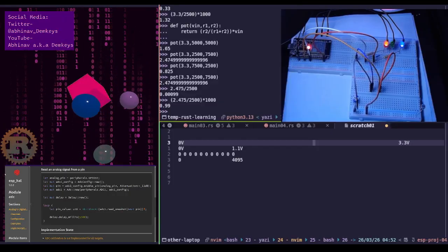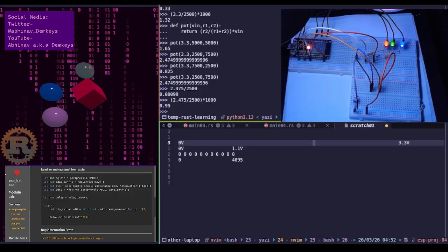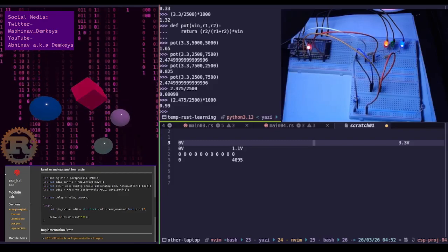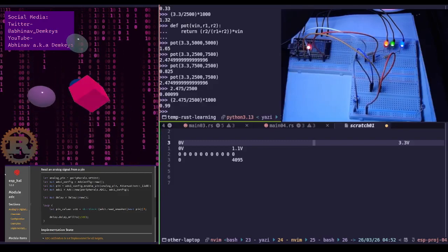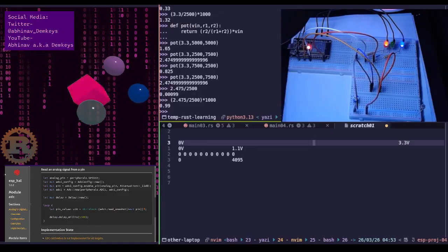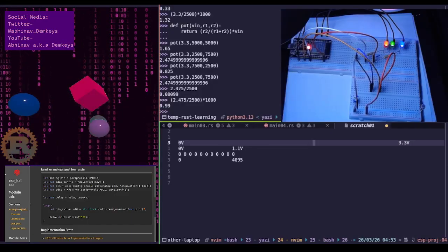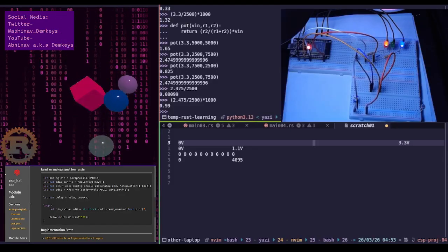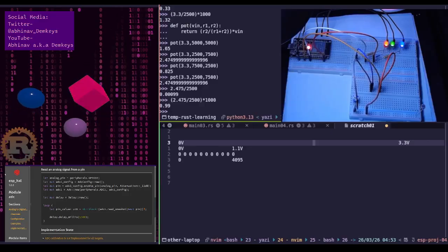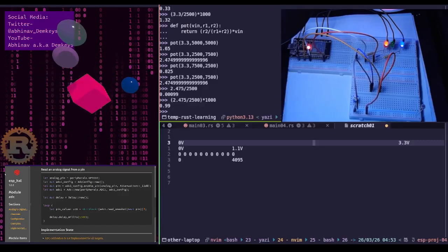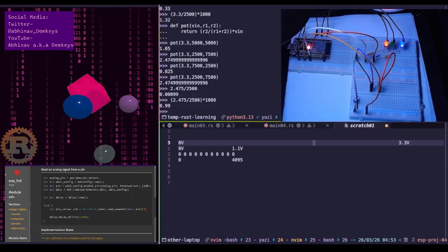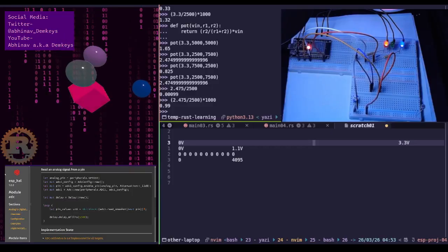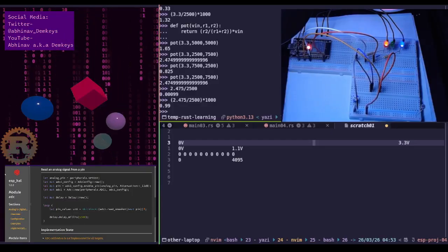Okay, the branch path into the ADC. The ADC pin is a branch off the main path. To calculate the current going into the ESP32, you have to use the resistance of the ADC pin itself, not the resistance of the potentiometer. As we mentioned before, the ADC input impedance is extremely high, typically around 10 mega ohms, which is 10 million ohms or more for the ESP32.